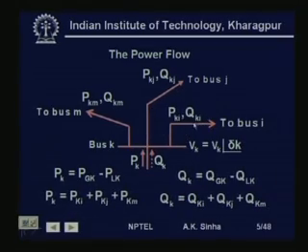If some power is flowing in, then that will be considered as negative power going out from this bus. Similarly, for the reactive power also, we have Qk, that is injected here, must be equal to all the reactive power which is going out from the bus. So, Qki plus Qkj plus Qkm, this is what we will get.